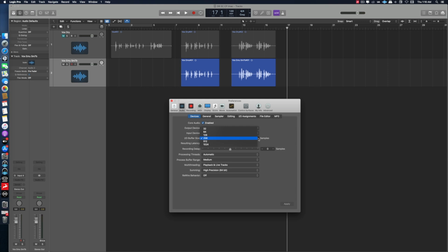But if you want lower latency, if you want to use a buffer size of 64 or 32, I definitely recommend Thunderbolt. So for recording, you can choose 256 or 128 if you are using USB, and if you are mixing, obviously we have to bump the IO buffer size to 1024. But if you are using the interface via Thunderbolt, you can use buffer sizes like 128 and 64. I usually use the interface with Thunderbolt and put the buffer size at 64.